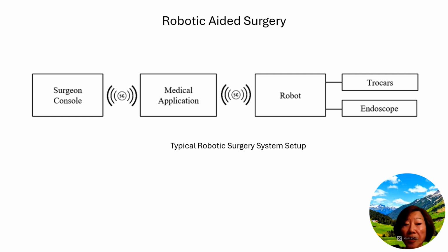Human tactile sensitivity is remarkably high, with tactile sensing bandwidths of about 400 Hz, referring to the frequency at which stimuli can be perceived. Consequently, haptic feedback systems generally operate at frequencies around 1000 Hz. This rate applies to the update of all information used in generating haptic feedback, such as instrument velocity and position.